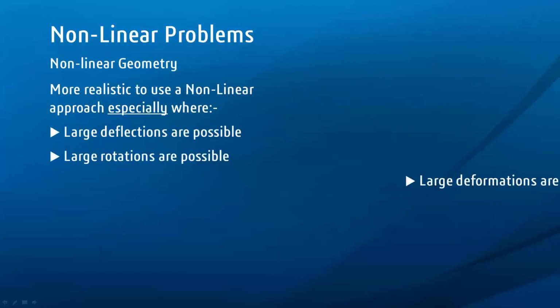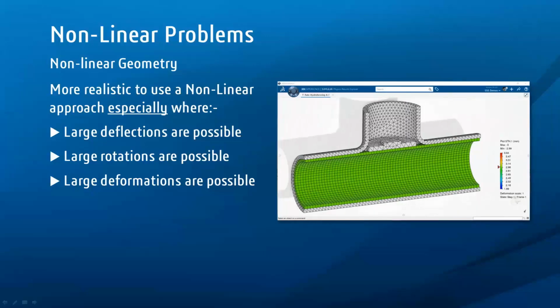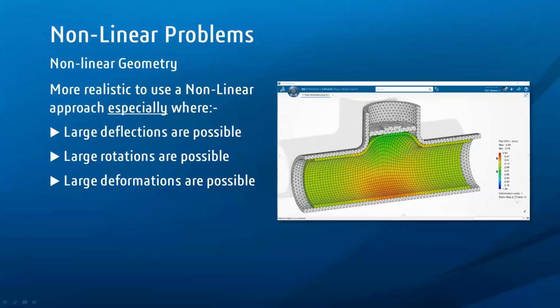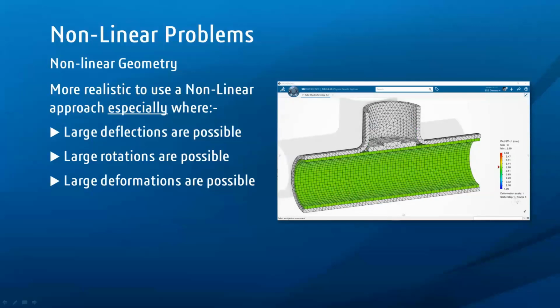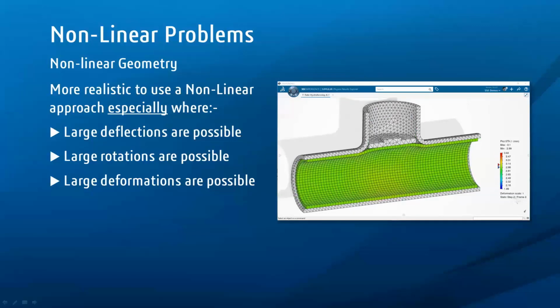In cases where the behaviour to loads is not fully understood, as in many analyses, it is more realistic to incorporate the potential for nonlinear geometric effects. This allows us to deal with dramatic changes in shape whilst retaining accuracy to real-life events that we are simulating. As shown in this high-performing example, there's a lot of motion in the mesh as it's subjected to these pressure loads, and we are able to capture these large deformations without hassle.